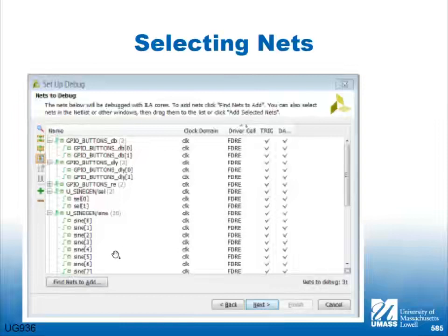So this is a limited one, but you can actually look at the graphical view of the net list of the chip, and you can click on it. It puts a little bug. You click on the actual lines that you want to probe, and then you compile your chip. And when you turn on Logic Analyzer, it already has all those signal names there for you.